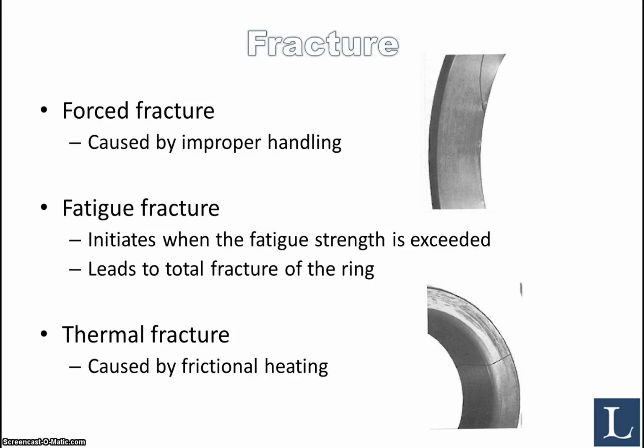Fracture can also occur for three different reasons. You have force fracture, for instance, caused by improper handling. There's also fatigue fracture that initiates when the fatigue strength is exceeded, and it leads typically to total fracture of the race or the ring. Thermal fracture may also be one reason for initiating fracture, caused by, for instance, frictional heating.